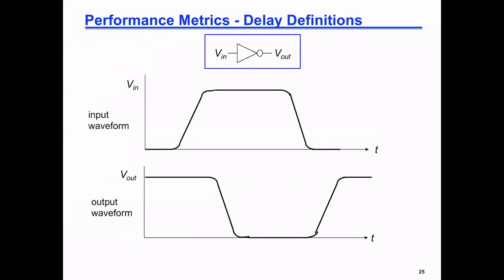Okay, so first, if I take it as a black box, the input waveform will result in an output waveform which has inverted logic. Meaning when this was low, this is high, when this is high, this is low, and so on and so forth. But what we care about is the 50% delay. We are going to make a definition which is TP high to low.